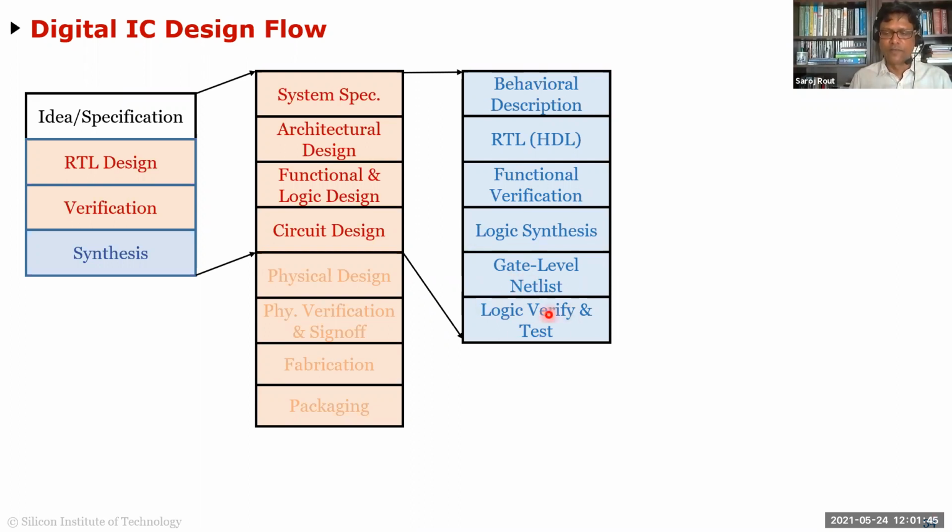And then you do the verification of the synthesized step. Like I was explaining in the previous slide, it's not guaranteed that if you have a behavioral description of your circuit that the synthesized circuit is one-to-one, right? As your circuit gets more and more complex, you might have more and more bugs in your gate level netlist. And this is something you need to verify after the synthesis, at the synthesis level.